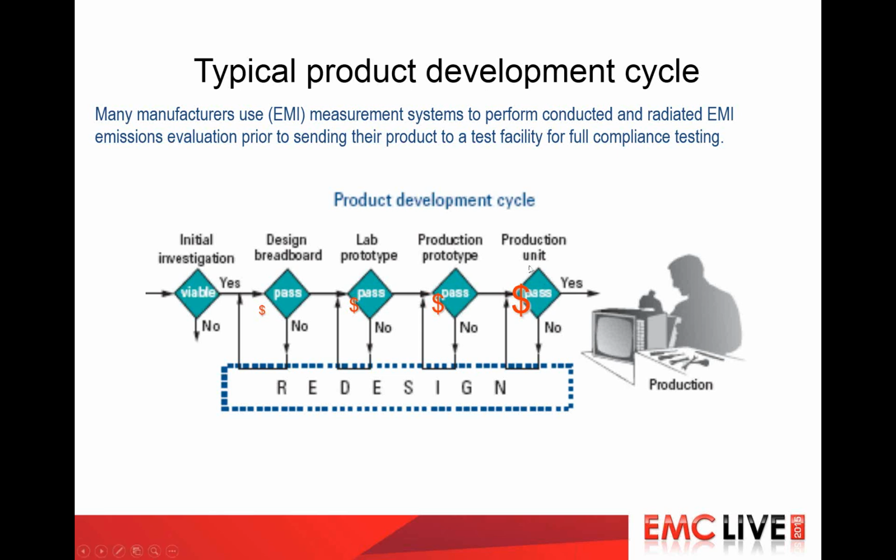It costs a lot more to do the changes here, to do a PC board turn or to reroute cabling, things like that at this end than if you catch it earlier. So that's the value of doing pre-compliance testing as you're developing the product through the design cycles.